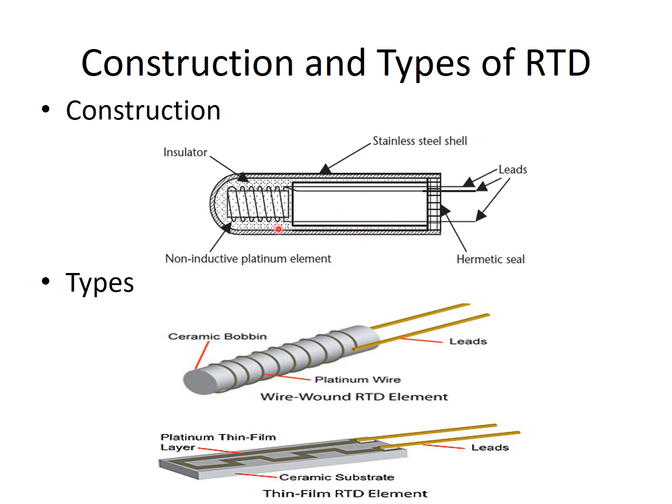Now, looking at the types of RTD that are normally preferred based on application, where we are going to place it, this is a rod type. Suppose we want to measure the temperature and convert it into the corresponding resistance in a running fluid for industrial purposes. Based on the temperature values we get the corresponding resistance values, so we can use this rod.